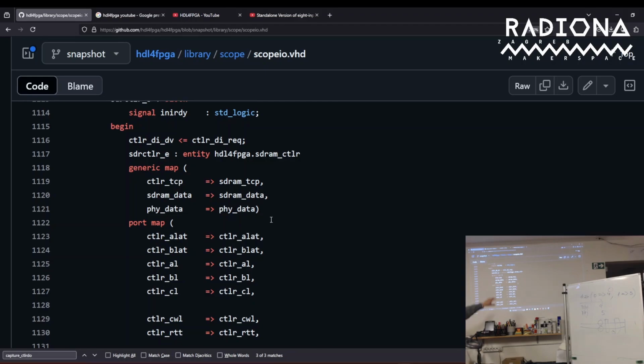And this is the controller itself. This is the DRAM controller. The SD in SDRAM has to do with synchronous, not the speed, because SDRAM, DDR, DDR2, DDR3, and DDR4 are all synchronous. So it's a generic name. What you have to do is only pass the frequency and the data. The data tells all the parameters of the DRAM. Remember what I was telling you about the different kits that have latency. You pass this here, and then you connect.